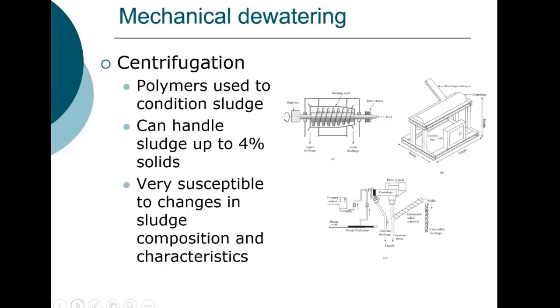A question about chemicals leaching into the aquifer from the sludge lagoon, yes. The East Lansing ones are lined, so you want to make sure that you have a lined lagoon so that you can minimize infiltration into the aquifer. The supernatant from the sludge lagoons, up until very recently, was piped back into the plant, to the headworks.